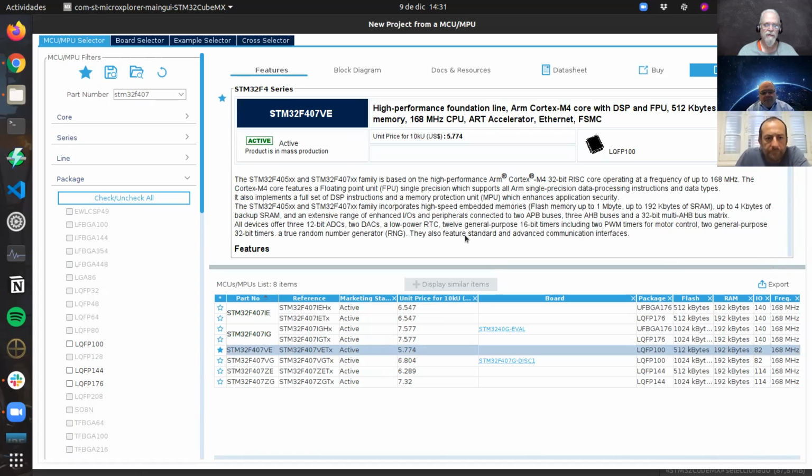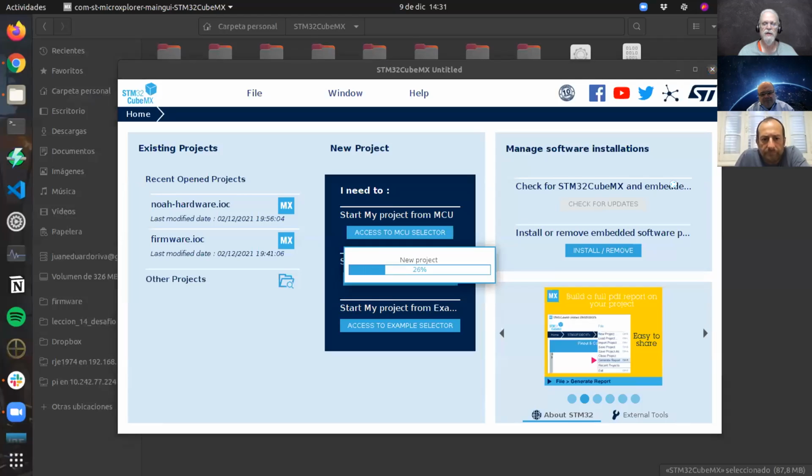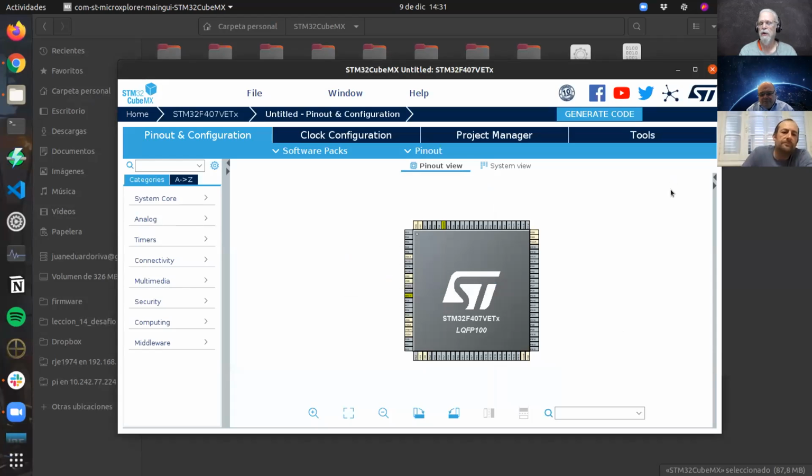And it could be that it's going to force you to pick. Well, over to the right, it simply says the package happens to be a 100-pin package, and I'm going to assume that's true. The other stuff you were looking at, out in the yellow area, all said 144-pin package, which is probably not what you had in the first place. So I might have been picking the wrong one. At this point, there is a 407 chip that's ready to go.